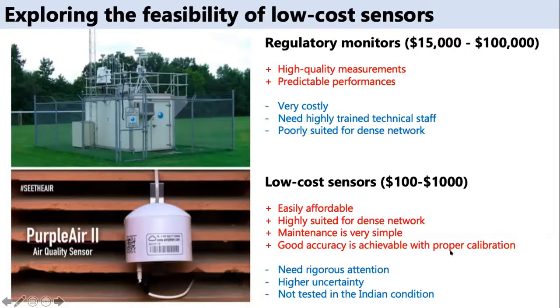However, I must mention that these low-cost sensors need rigorous attention because their uncertainty is a little bit high, so they need periodic calibration. And so far, they have not really been tested in Indian conditions. Only recently we have started testing various low-cost sensors in these Indian conditions. By Indian conditions, I mean most of the low-cost sensors are tested in developed countries where the air pollution level is many-fold lower than the pollution level in India.